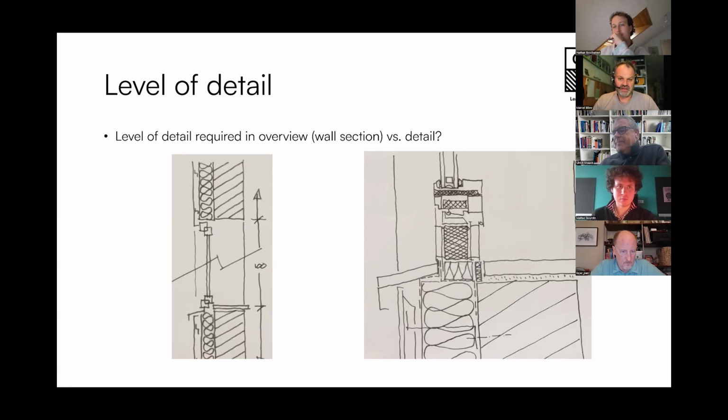What we've often done within projects, when the project was big enough, is that you are allowed and able to design certain parts of extrusion profiles that make your facade more customizable, more special, because maybe you can integrate sunshades. That's what we did. The architect wanted a special framing around it. So within the existing system, we could make customized extrusions that fit within the system.